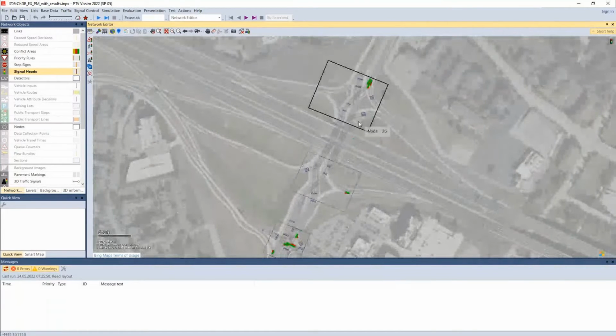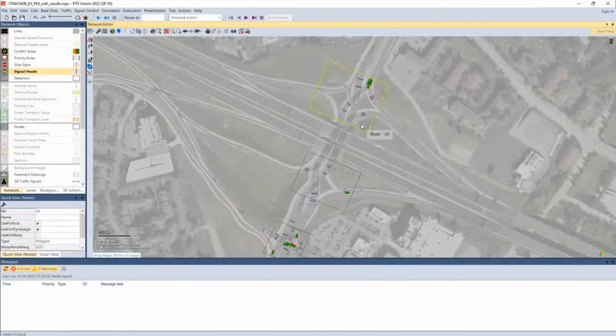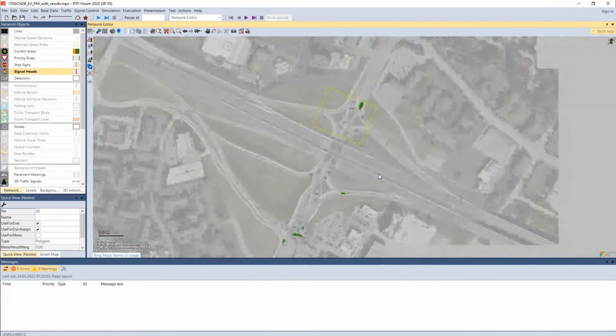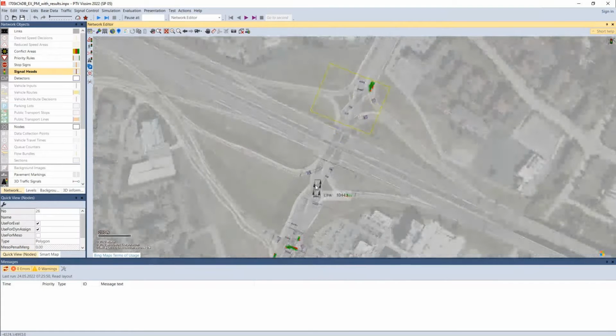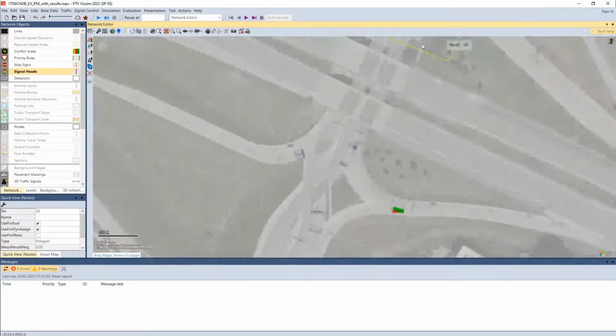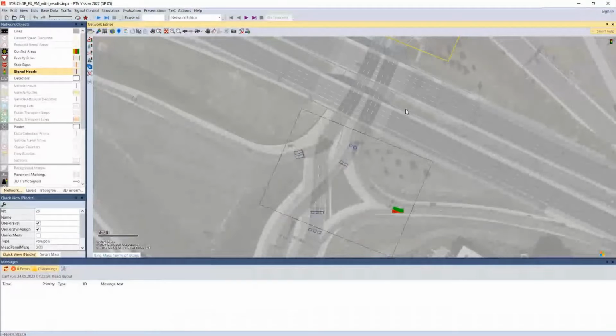And you'll notice that in the way this one is modeled, both sides of the diverging diamond are modeled with two different intersections. That's very common to do at the intersection capacity analysis level, right? Your HCM level or your travel demand modeling level. It's very common to have those modeled as separate intersections just because of the way you're going to handle it. But in Vissim, these could be modeled as one intersection. It just depends on how you want to analyze the network.